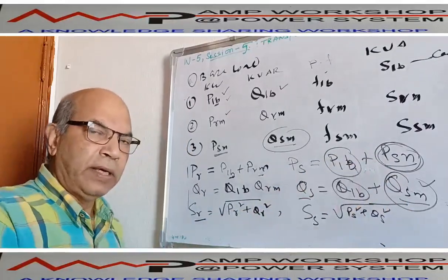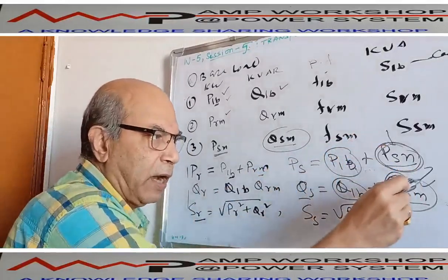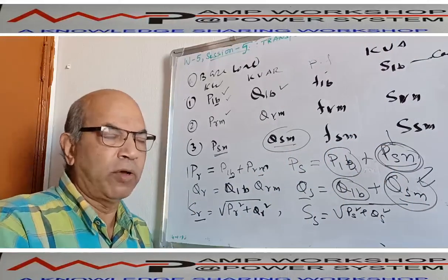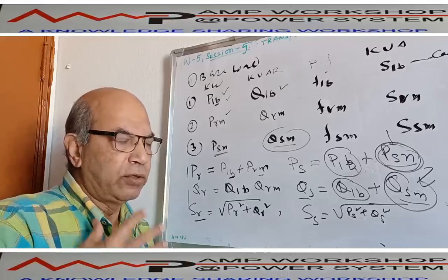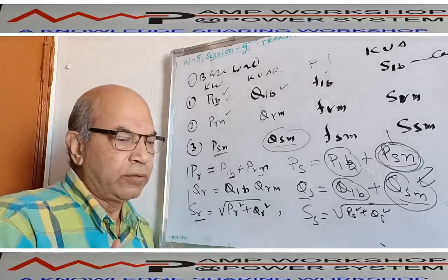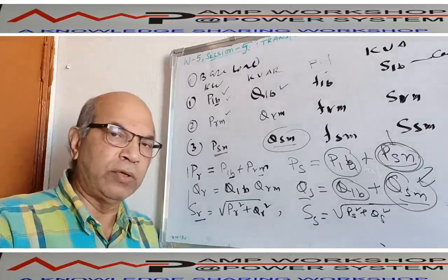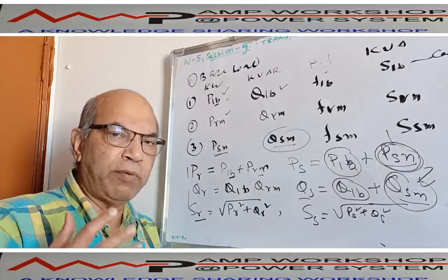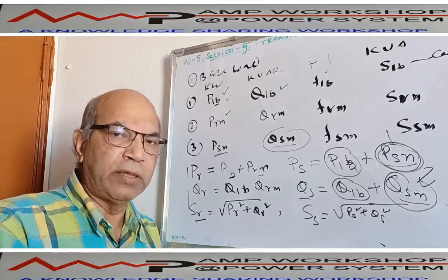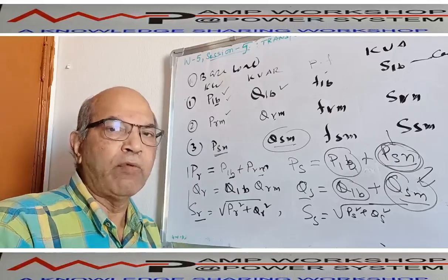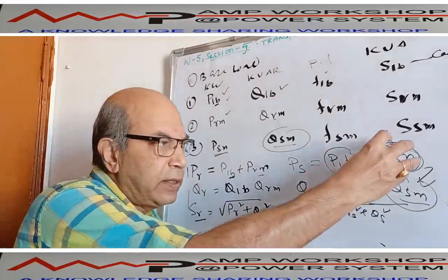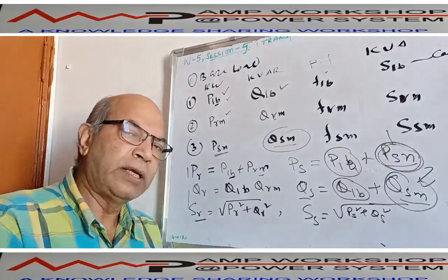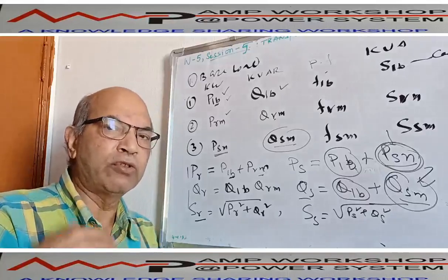Now we have said at the starting, how much time will this flow? It is only 6 to 15 seconds, because motor starting time is normally 6 to 15 seconds. So during that time, the motor can be overloaded. If the motor is running at either 50% or 70% or 90% loading before motor starting, we can overload the transformer by 150%. That means the starting kilowatt requirement of the motor and the reactive part of the motor can be catered by the transformer using its overload capacity.